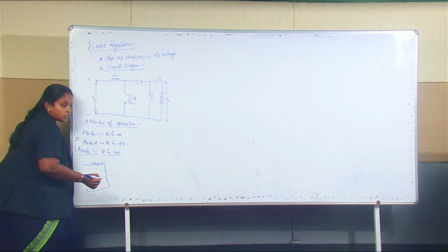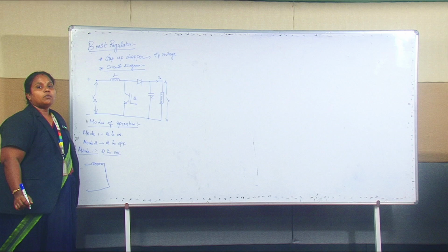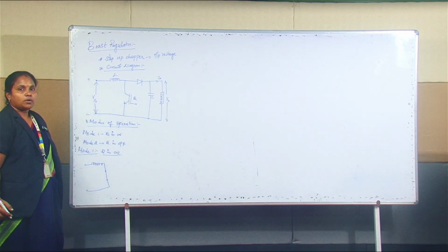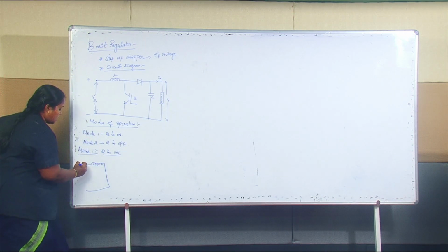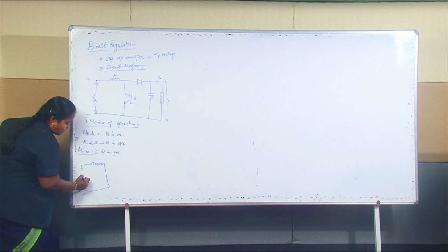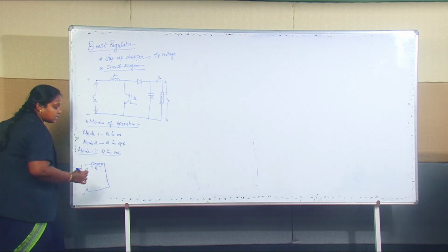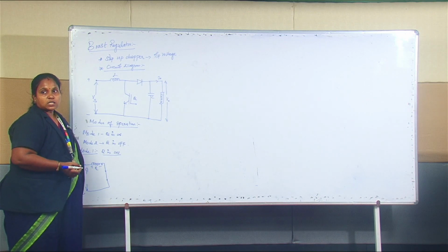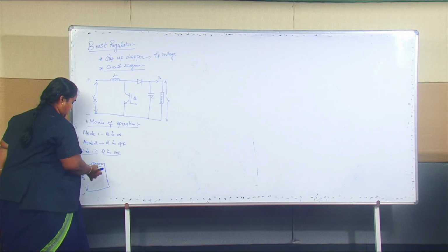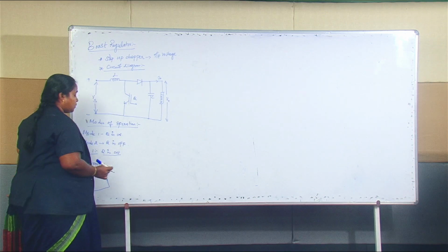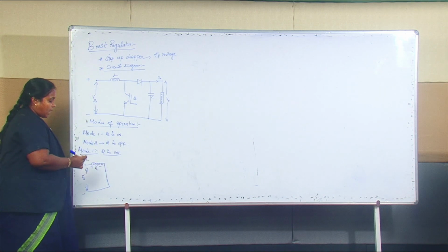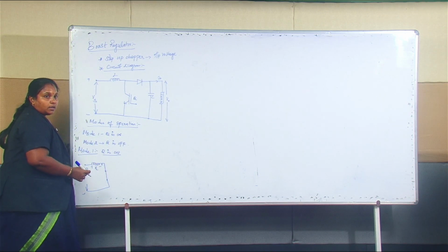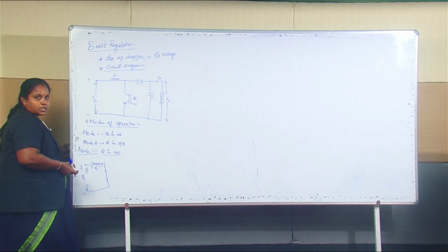Here your switch is on, right? As I said before, when we are considering your switch to be on, we have to draw it like a shorted path, right? So it is a supply, and we have a voltage across this. Let it be in the charging mode, so the polarity is assumed to be positive and negative. So this is the mode 1 equivalent circuit, from which we can obtain a voltage across an inductor to be